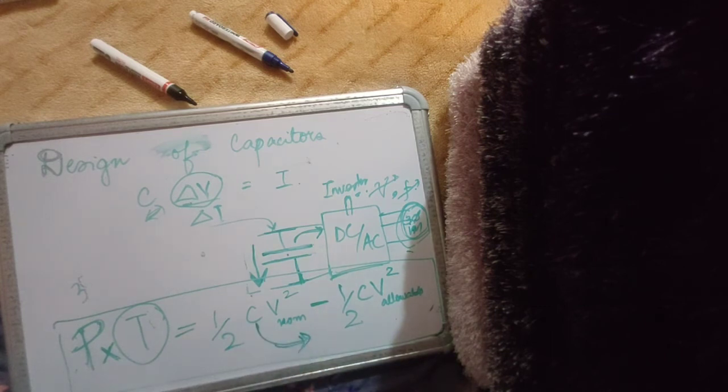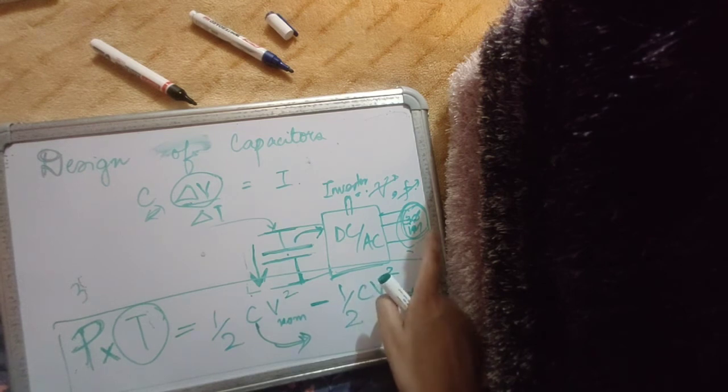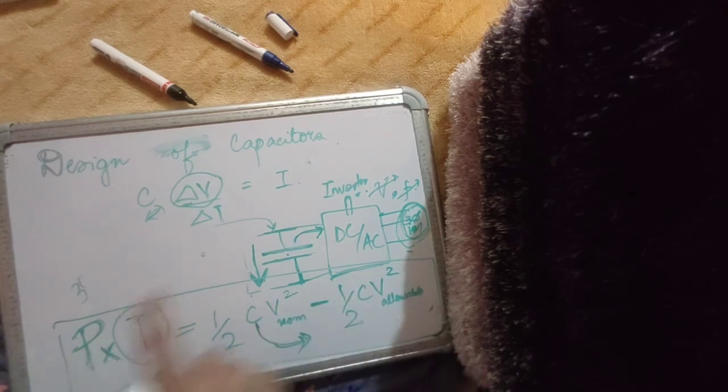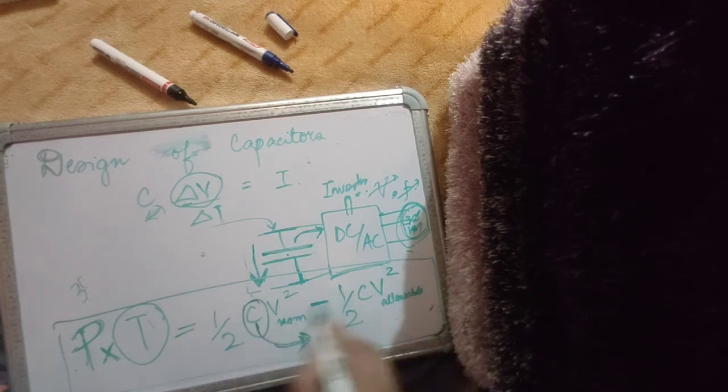Sometimes they are also used for fault ride through like this. So you decide what the nominal operating voltage is, what voltage you can allow the capacitor voltage to fall till, say 80% of the nominal or 90% of the nominal, and then for how long you want to sustain, for 2 cycles, 3 cycles, 5 cycles of interruption, you want to sustain your load and continue delivering rated power to the load. That's how you will find the value of C. So this is also about choosing the value of capacitors to supply the energy demand of the load for momentary interruptions, and of course voltage ratings depending upon the circuits in which you have connected.